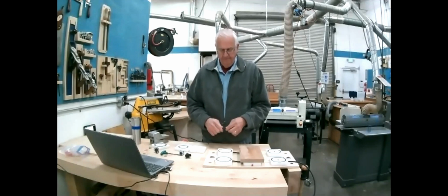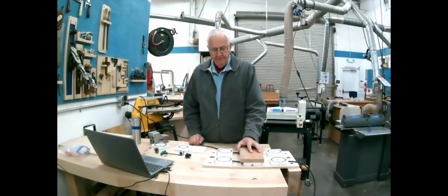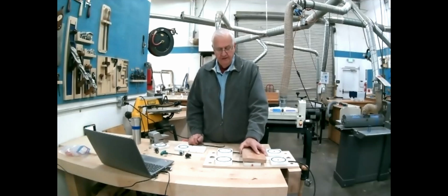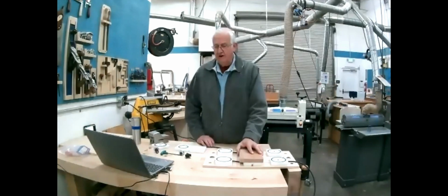Now that's absolutely true for vacuum bagging, but for vacuum clamping, it's also a function of how much leakage you've got around your connections. So you need to be able to keep up with the leakage around your joints. But if you're doing just a couple of 3 pucks, I did it with this 6 puck setup I've got. I've done it with a small pump, and you'll be fine.